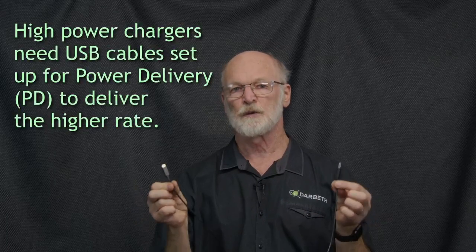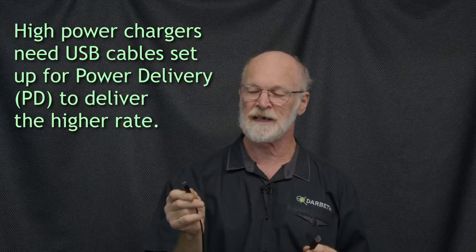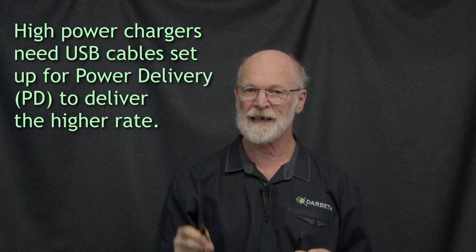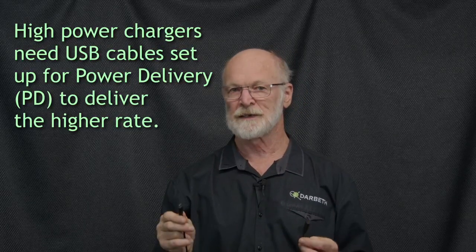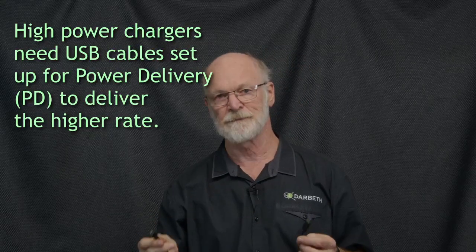So if you have just a standard old USB-A cable, you will get the old charging rate, because it needs the extra pairs in the USB-C cable to understand what the capability is of the device you're delivering it to. That's called PD, or power delivery.